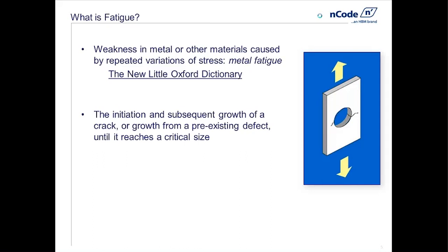Other things to keep in mind with the definition of fatigue is that all fatigue phenomena are caused by cyclic loading. If the loading doesn't change, then we don't have a fatigue problem. When I say loading, actually I should be careful about that. If the stresses don't change.